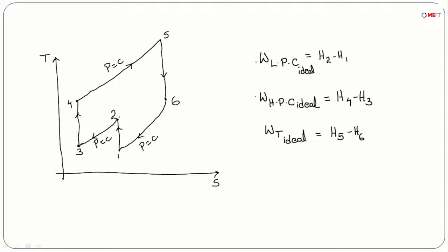If we use a normal Brayton cycle, this will be isentropic compression, then heat addition starts from this point to here, and then expansion takes place. But here, because of heat rejection in the intercooler and again compression, we need to additionally supply more heat in this particular case.